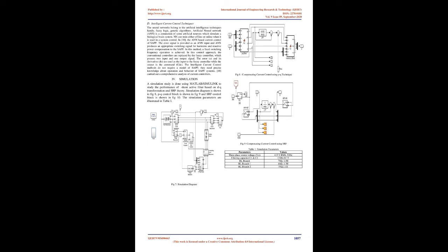The calculated currents from Eq. 4 are the fundamental positive sequence reference supply currents, which meet the fundamental positive sequence load to maintain constant DC bus voltage. This ensures compensation of harmonics, reactive power, and unbalancing. Hence different components in the load currents are extracted successfully using SRF theory. The source current is controlled to follow these reference fundamental positive sequence currents by switching the VSI through different control strategies like hysteresis current controller and sliding mode controller.